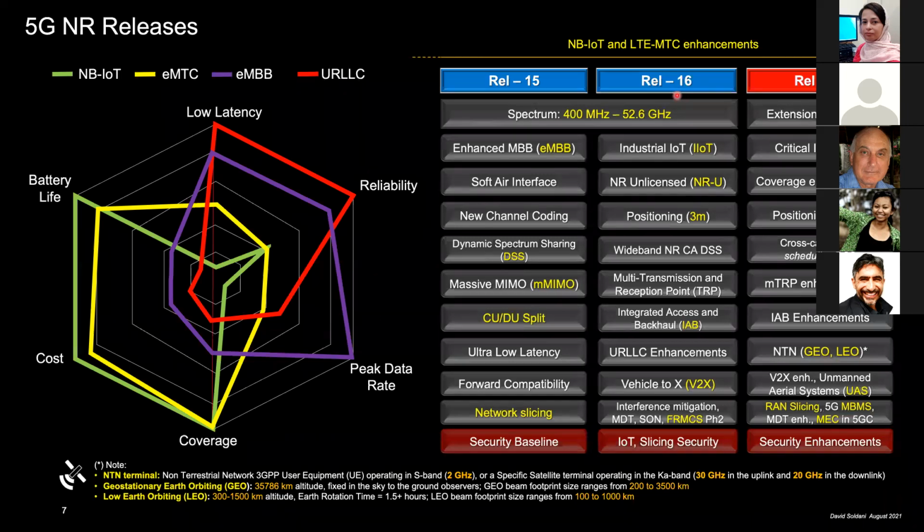So what does the new radio do in practice? It supports from the very beginning very interesting features, or say technologies. We have massive MIMO from day one, which was an optional feature for LTE. For the new radio, it is a mandatory requirement. So when you go on air and you offer that commercially, you must support massive MIMO. So you need to have a capability in place to use multiple antennas and direct the signal through multiple beams simultaneously. So you may serve all those beams to a single user, or you may think of having a multi-user type of approach, where you have different layers provided to different users at the same time. You have a sort of space diversity in that sense.